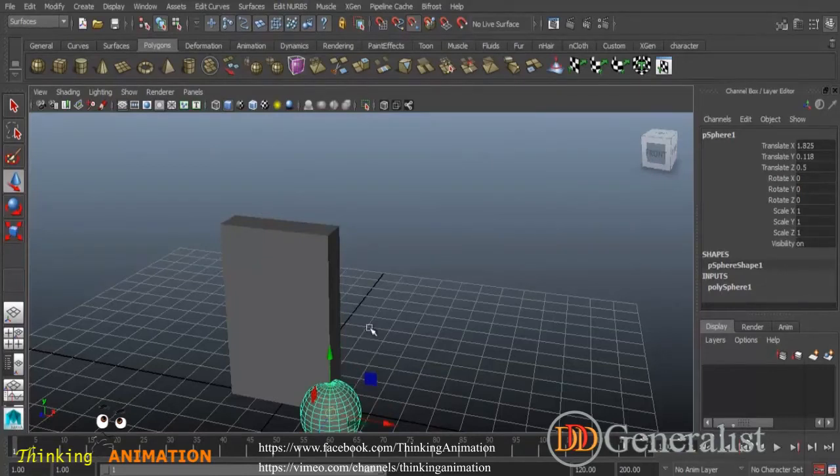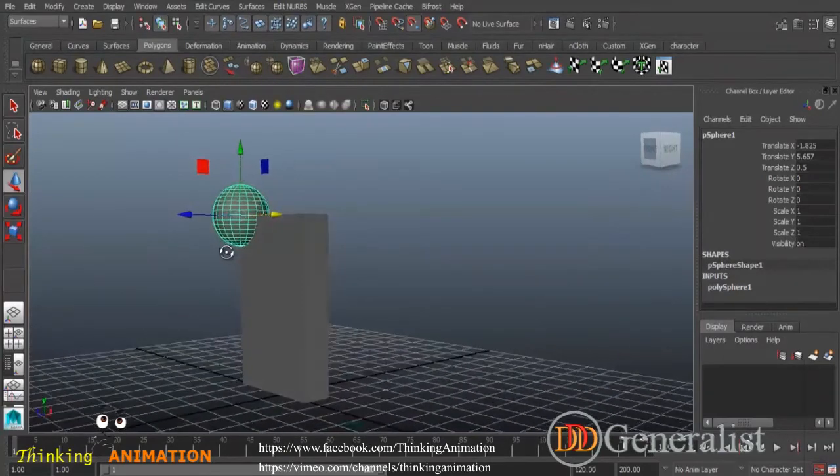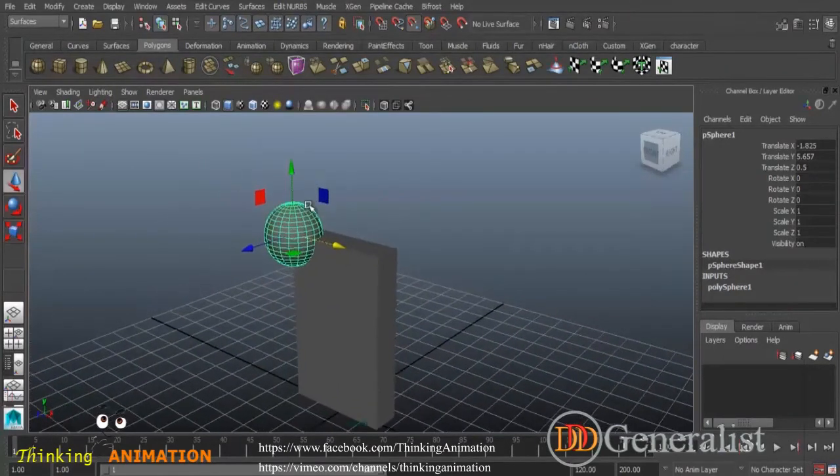But what I just want him to be snapping on y-axis only. Just select the y first, and if you now move him on to anywhere, it will only snap on the y-axis. It won't move on the x or the z-axis. Even if I want to move him here, it's not working. But when I select the x-axis and now I want to snap him here, it will snap. So you can move him. You can just target him onto any axis by just clicking that and then just moving it around.